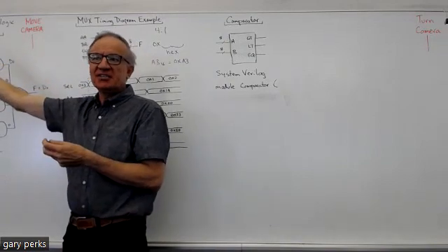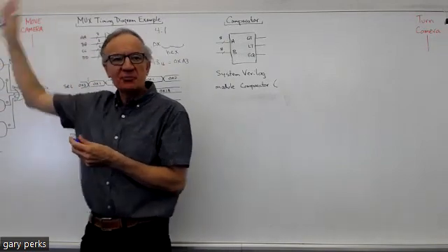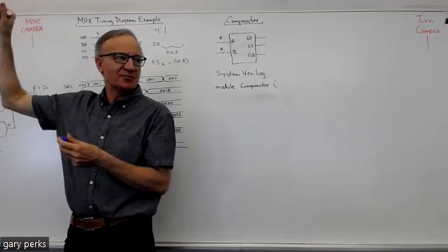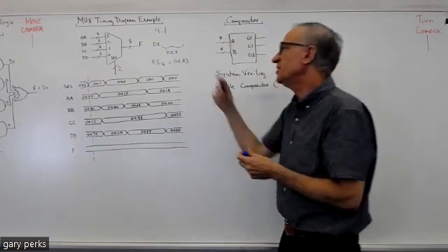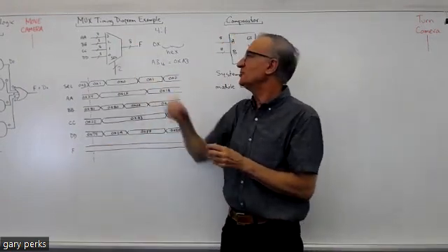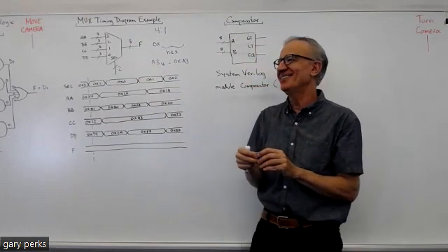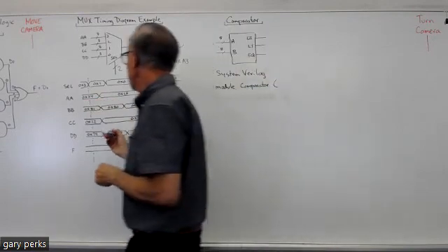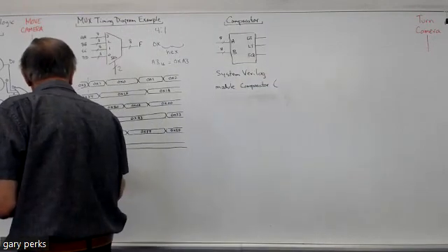That's just to show that when you have a MUX symbol like this, the numbers for the inputs can be either top to bottom or bottom to top. It can be either way. So what's the data going to be now that you realize it goes 3, 2, 1, 0 instead of 0, 1, 2, 3? Right, it's going to be whatever's on the AA input. So it's going to be 24 hex.